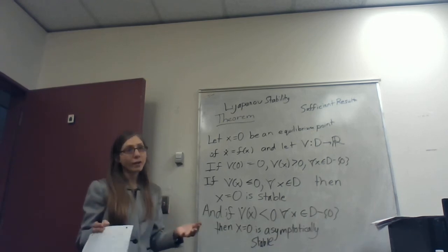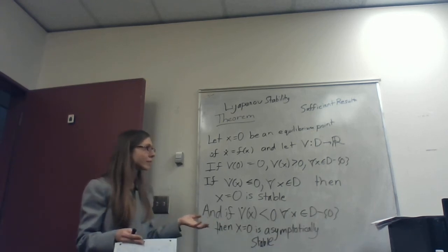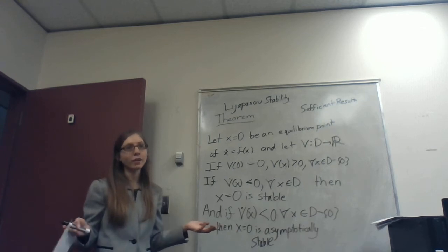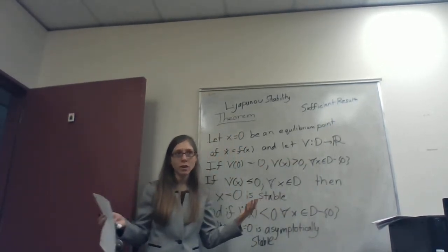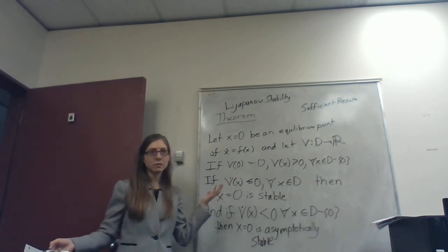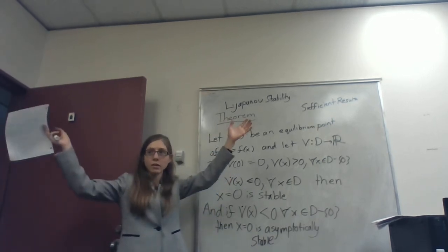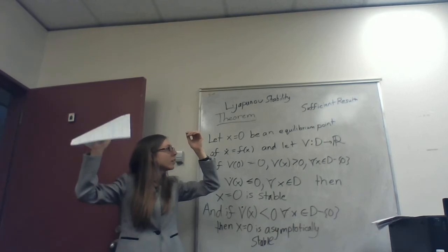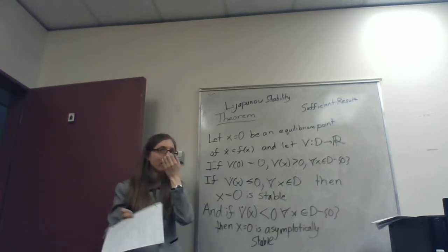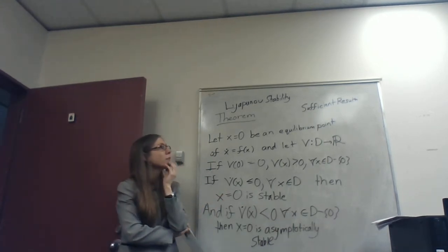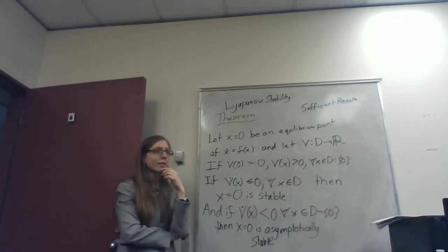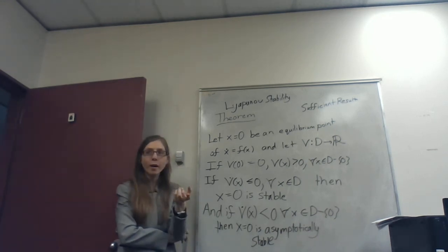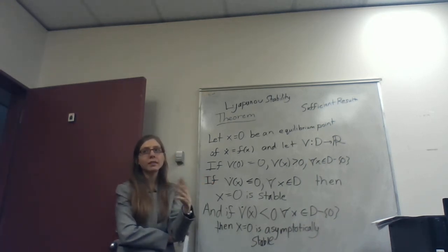This is really hard for industry to work with and scale to a very, very large system, because V has to be a function of all your states. Imagine that you have 1,000 states because you have a huge refinery. It's big. Then this just gets really hard to work with. So industry is not super into Lyapunov-based MPC, but it has really nice provable properties. So something that is in the current work